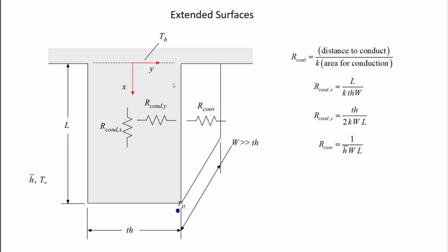There's a different level of difficulty associated with moving energy by heat transfer, by conduction in the X direction, so there's a thermal resistance associated with that, by conduction in the Y direction, so there's another one associated with that, and then by convection from the surface to the surroundings, so yet another one associated with that. So these are approximate concepts, right? Clearly, I can't just somehow combine these resistances and get an exact solution, but that doesn't mean that by calculating these resistances and looking at their magnitudes, I can't understand the problem pretty well.